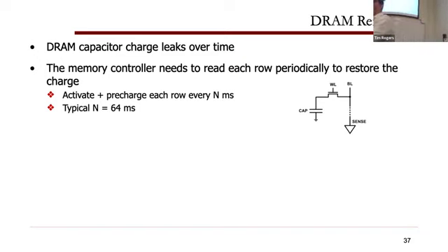That's not what a DRAM cell looks like. That's way too many transistors and way too expensive. DRAM cells are much smaller. They essentially have this thing called a trench capacitor. The nice thing about the SRAM cell is that these inverters are plowing electricity at each other, so they hold the signal by themselves because of the construction of the circuit. That's not what we do in DRAM. In DRAM, we just charge up a capacitor, and whether the charge is on the capacitor or not determines whether there's a 0 or a 1.